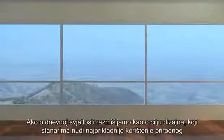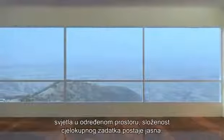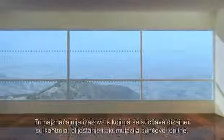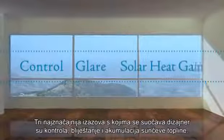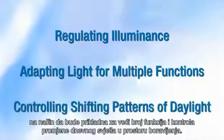If we think of daylighting as the design objective that offers occupants the most appropriate use of natural light in a particular space, the complexities of the overall task become clear. The three most significant challenges faced by the designer are control, glare, and solar heat gain. There are three basic dimensions of the control task: regulating the amount of illuminance to fit what is needed for normal work, adapting the amount of light in a space to fit multiple functions, and controlling the shifting patterns of daylight in the occupied space.